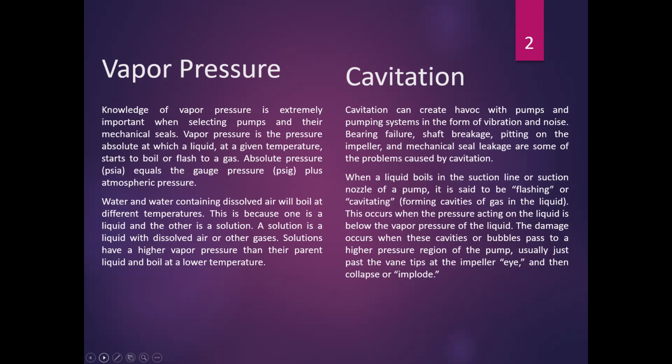Next is cavitation. Cavitation can create havoc with pumps and pumping systems in the form of vibration and noise. Bearing failure, shaft breakage, pitting on the impeller, and mechanical seal leakage are some of the problems caused by cavitation.